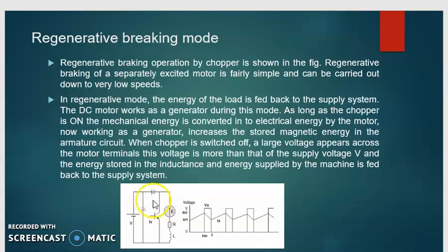When the switch is on, that is the transistor is on, back EMF has positive voltage, so the freewheeling interval starts. A current starts flowing from collector to emitter of the transistor through this circuit. In this direction, freewheeling currents flow. This interval is also known as the energy storing interval. Here the armature voltage becomes 0 due to short circuit condition, because when the transistor is on, this circuit is shorted and VA across the armature circuit becomes 0.